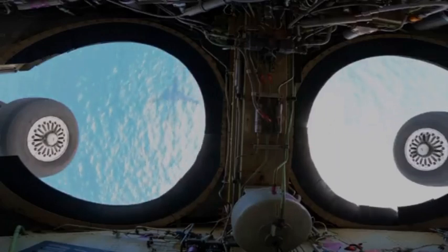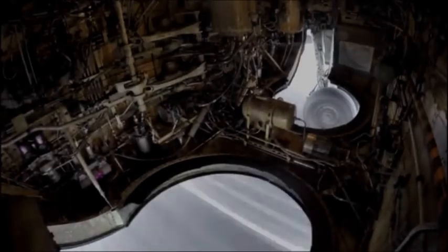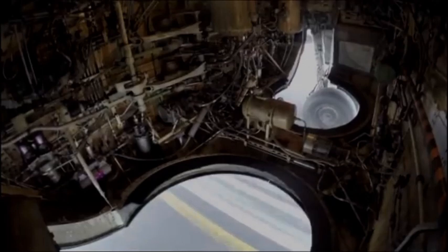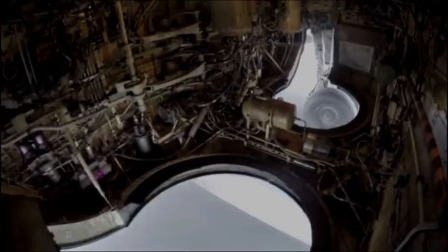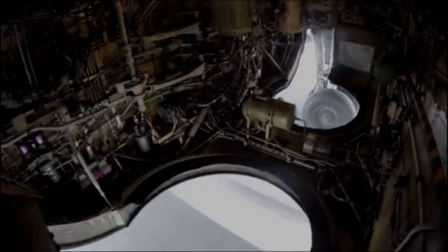Once the landing gears are retracted, we have mechanical locks, and the mechanical locks will lock the landing gears in the up position, and we do not need hydraulic pressure continuously applied on the landing gear to keep them up and locked. So once they are retracted and locked, we can relieve the hydraulic pressure on the landing gear system lines, and they will remain retracted with the up lock mechanism.